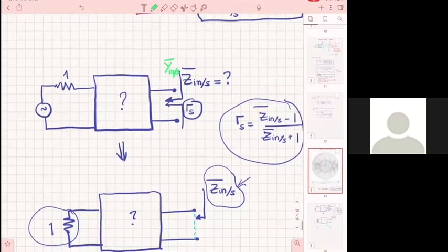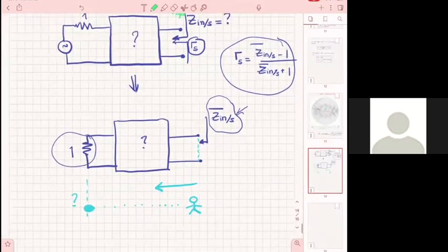All right. So in this case, I will not use normalized impedances. I will erase that, and I will use a normalized admittance. But this still remains 1, because when I normalize admittances, I normalize with a characteristic admittance. So a 50 ohm impedance is 1/50 in admittance, and I will normalize with 1/50. So it gives me always 1.